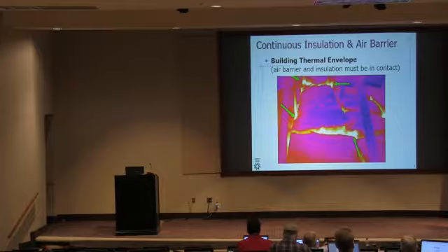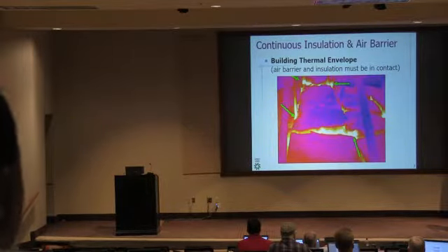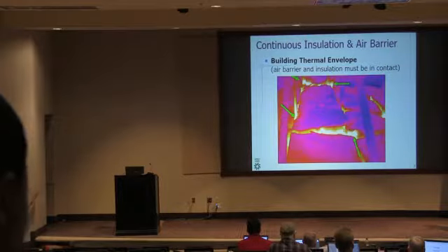And you've got a space up there, yeah, it could be 40 degrees in the winter, and you're trying to keep it maybe 70 inside, that's a 30-degree delta T, but it could be 120 degrees in the summer. You're trying to keep it 70 inside, that's a 50-degree delta T. That's why we put so much attic insulation in anyway. Big delta T, big temperature difference.